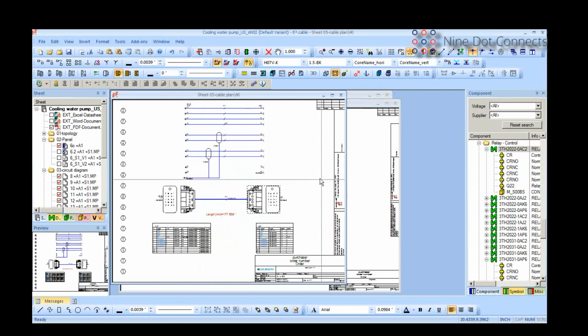And the difference between this type of definition and a form board is that it is actually created to real world dimensions, as opposed to me drawing it and giving it a length. So you could actually plot out a form board sheet onto plywood and actually use that as the base for building a cable, harness, and so on.